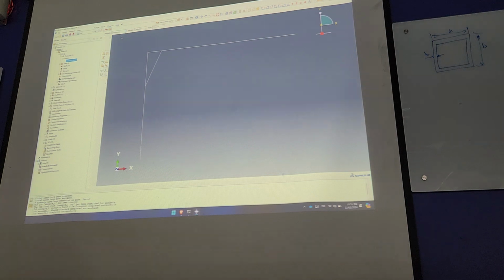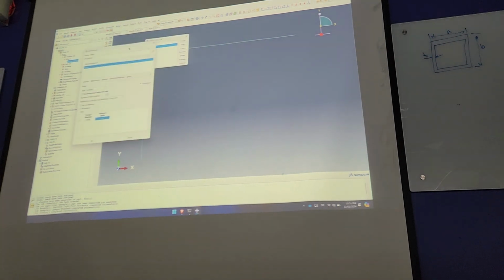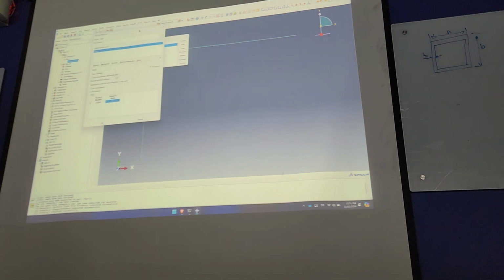Nothing new in it. Now in property, I created material and used values. Again, we will be using only elastic material, so there are only two material properties that we are after: Young's modulus and Poisson's ratio. We are not interested in yield or what happens post yield, plastic deformation.